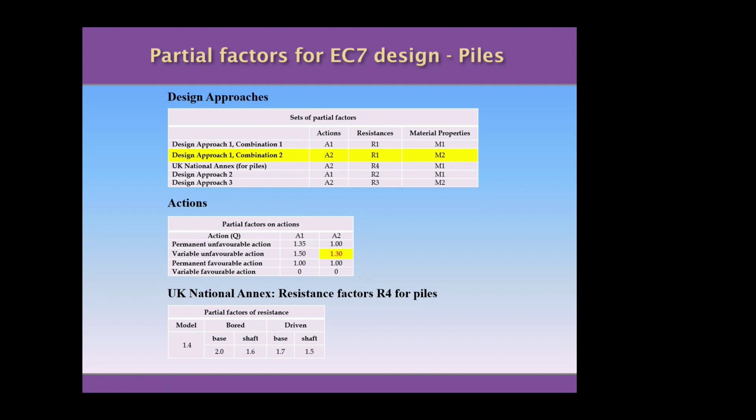So we divide the capacity we calculate to reduce it, considering that this is a calculation we make using a model, a very simple model. Because it's not exactly the reality, we need to reduce this capacity in order to follow the advice of Eurocode 7 and to be safer when we make a decision and we sign a design, for example.